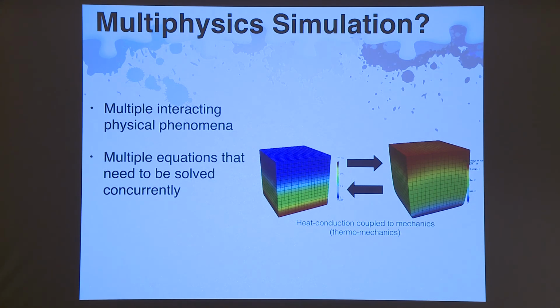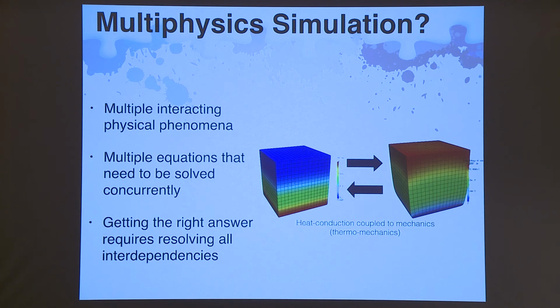And there's a lot of different ways you can actually go about achieving a multiphysics simulation, okay? But the basic problem is that we saw that huge bubble diagram of, I don't know, however many, 30 different bubbles or whatever, right? And so you don't really want to just pass back and forth between all 30 of those bubbles. It's not really going to work out. So you really need to take a more sophisticated approach at developing your software so that you can actually solve for all these different physics and resolve all the interdependencies.